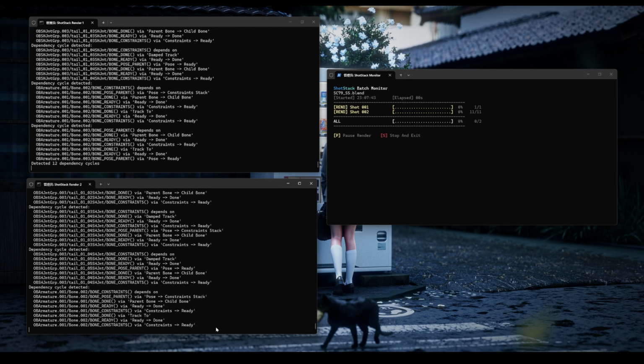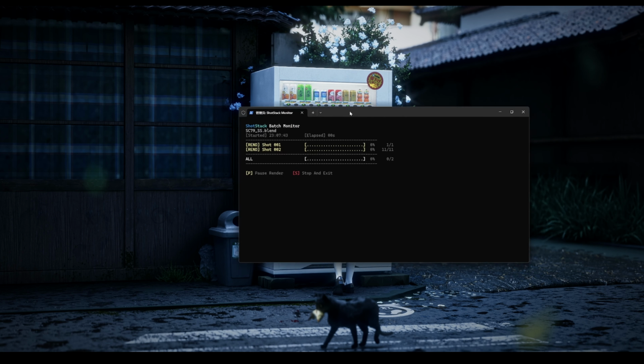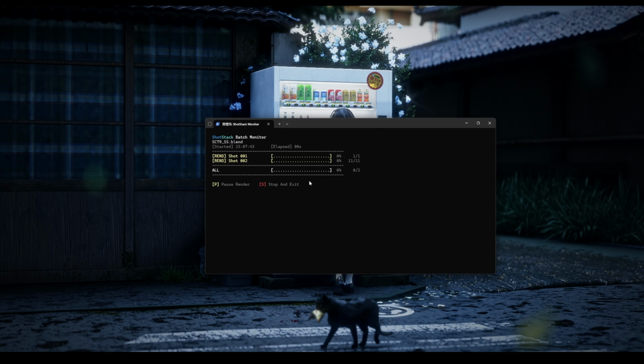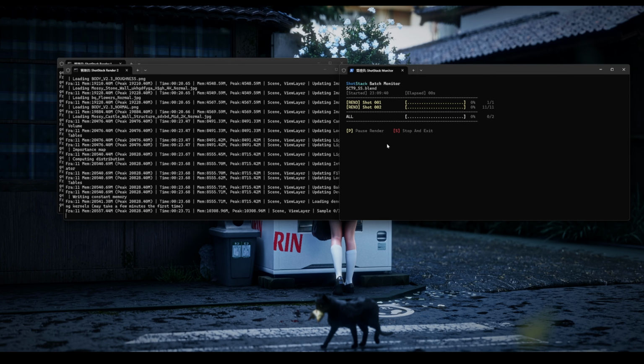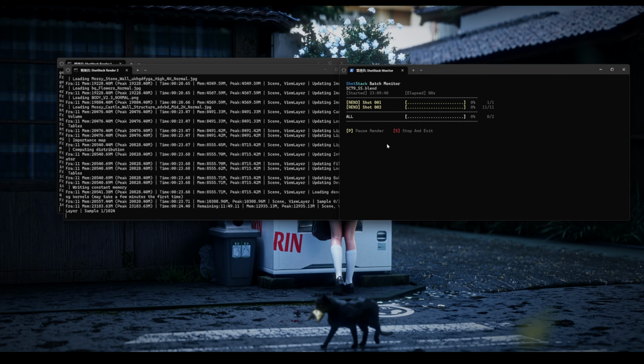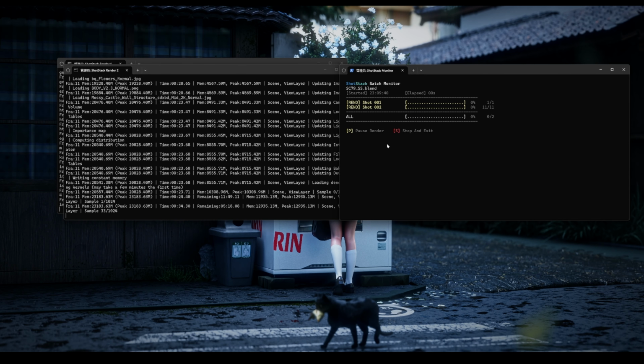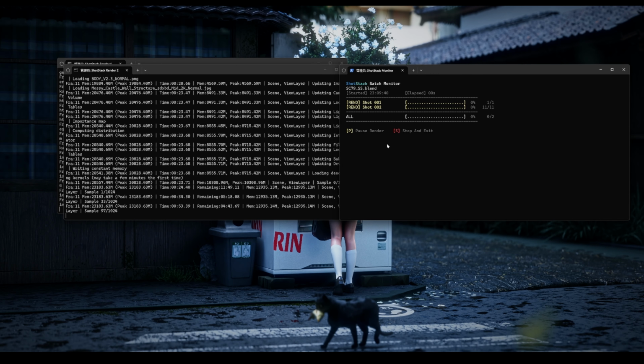of every individual shot. When we open a Blender file, the viewport takes up a large portion of the GPU memory, sometimes several gigabytes of VRAM. If you have a very large amount of RAM, then you don't need to worry too much. But even when I use 24 gigabytes of RAM, sometimes there still isn't enough, and there can be a shortage of RAM, forcing you to use system memory instead. That will significantly reduce your GPU's rendering efficiency. So when we're doing this kind of rendering, it's best to close Blender's interface itself and turn off the viewport and use command line rendering instead. That way we have more space for rendering.